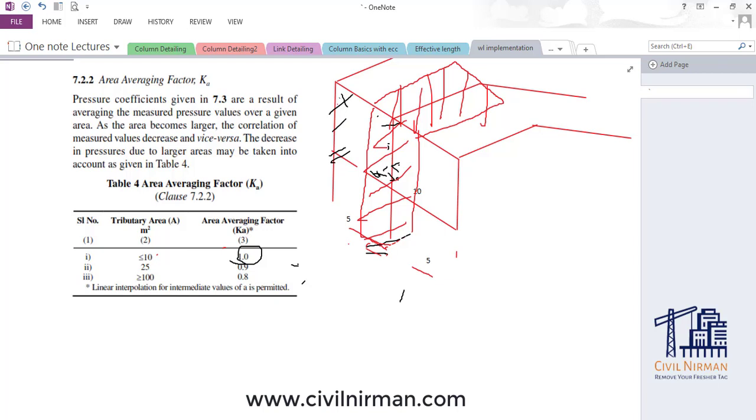But if you have RCC column up to 3 meter and then your steel frame starts, then you have to go with that much height, because for RCC column wind will not have much impact. In the analysis part, whatever section you are designing in STAAD Pro for the PEB design, for that much component you have to apply your wind load.